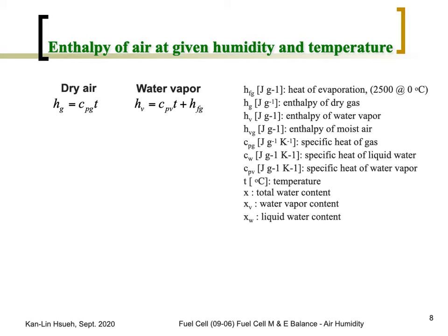And then the water vapor: the temperature times the specific heat of water vapor, Cpv, plus the HFG. The HFG is the latent heat, the heat of evaporation. From liquid water to vapor, how much energy is required.